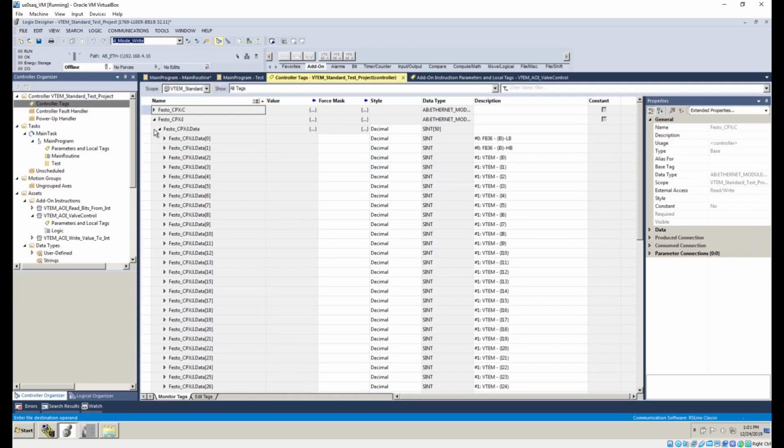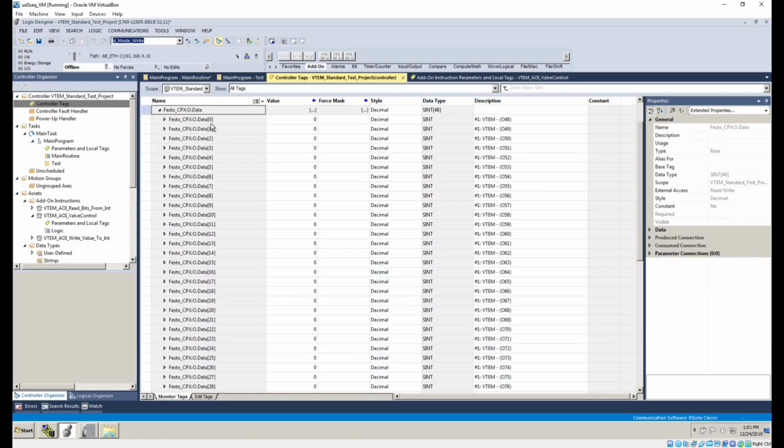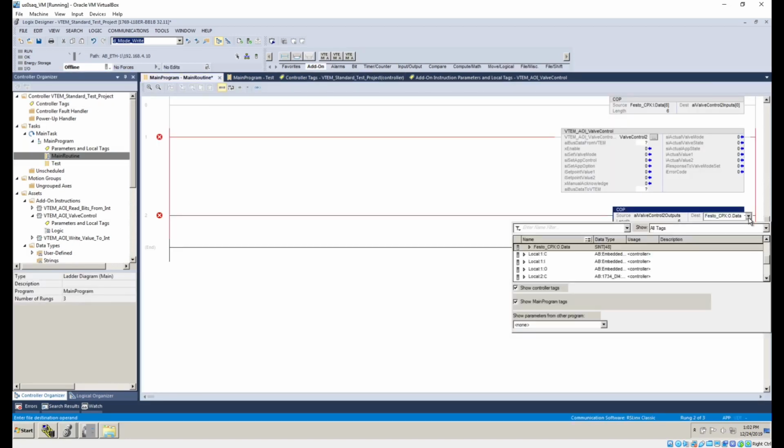And then here we don't have any diagnostics, so this is important too. On the outputs, you see here I have 2 bytes for diagnostics from general diagnostics out of the terminal. On the outputs, I don't have that. I have just the outputs, right? So I don't have those first 2 bytes of diagnostics. So that means that if I go here, and remember that I'm working with the second valve, and I look for that output data, this is my first valve, and each valve occupies 6 bytes. So 1, 2, 3, 4, 5, 6. This is the next. So this is valve number 2.